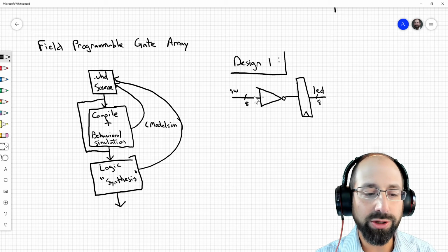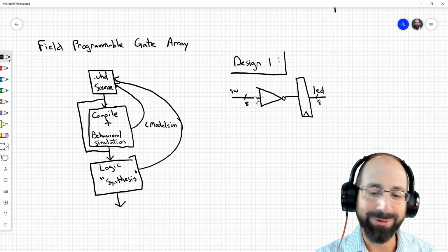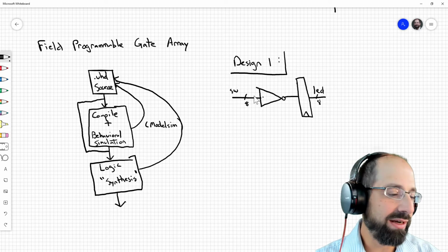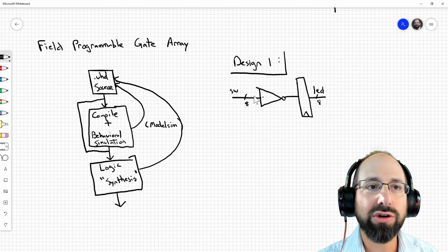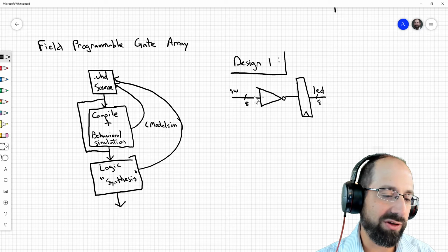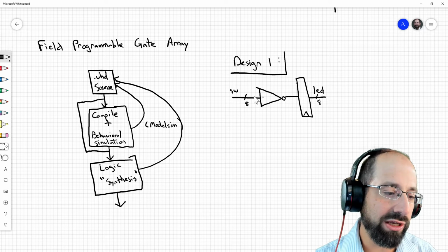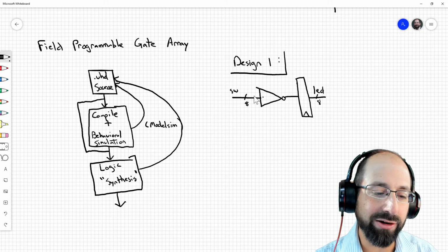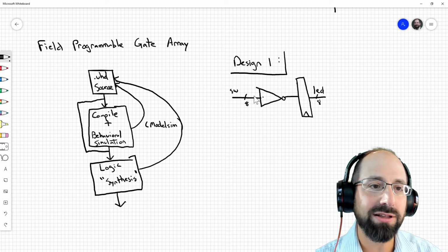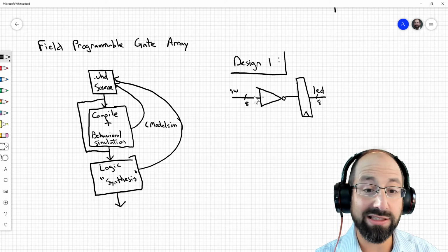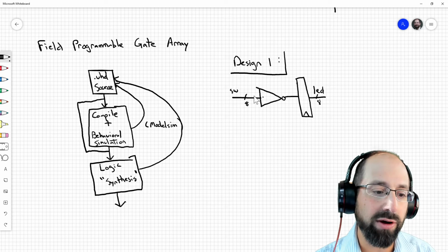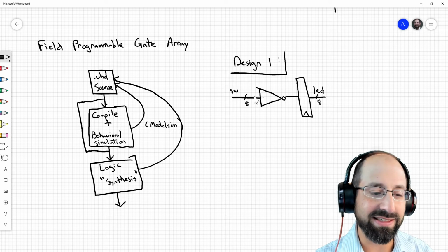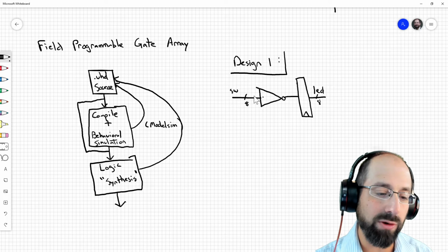You're either looking good or you're not looking good. And that's another reason why you would potentially have that feedback path here. Not just errors in terms of you didn't have a complete sensitivity list in your VHDL code, or you did something a little creative, and it's just not going to work in terms of hardware. It's also potentially a failure point in that your design just isn't going to fit. It's just not going to work the way you want it to.